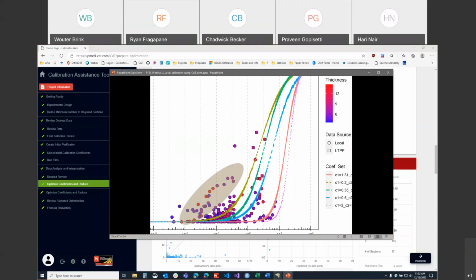And verification could be run basically at any time, but to avoid using a lot of resources, I think we've suggested 5 years to at least look at the initial verification based on your older coefficients to see if anything has changed. And then you make a decision if you do need to. If there's no significant difference, then you don't need to recalibrate.